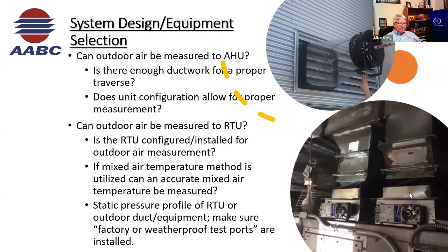So we're at a major crossroad here about how to accurately test outside air coming in on this second picture. Is there enough ductwork for a proper traverse? Does unit configuration allow for proper air measurement? You know, when we have these situations, again, right here to the top right with that picture and down to the bottom right, the answer is going to be no.